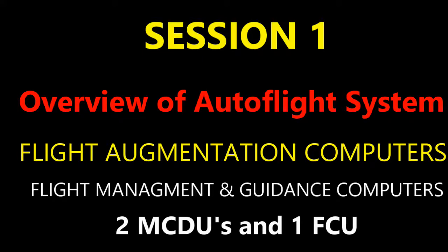Okay, and then of course you got your MCDUs on your center pedestal. Okay, so you've got those readouts, and that also just incidentally is where you're going to be doing your system testing. So you got your system report and testing. That's where you hit that and run some warning tests for the Autoflight system. Okay, that's a side note. All right, so on AFS control and indication, you have different columns. There's 5 of them. So you've got columns for your lateral modes, your vertical modes of the aircraft, and you got auto thrust operation as well as your approach capabilities.